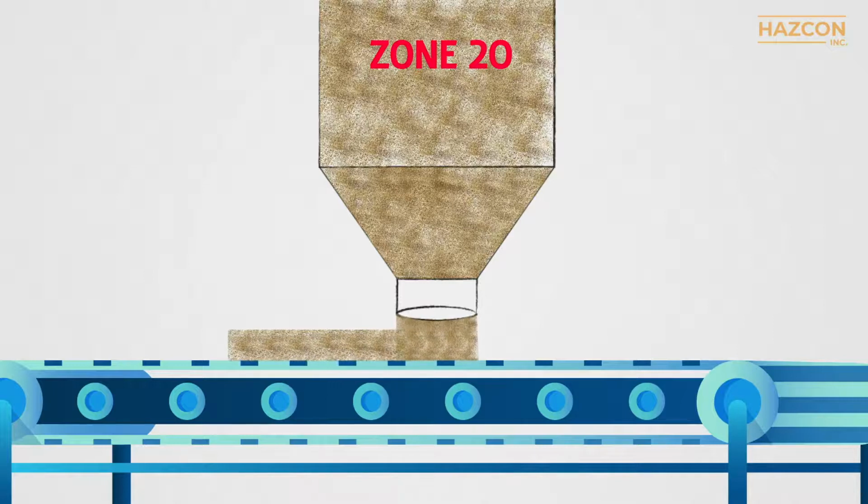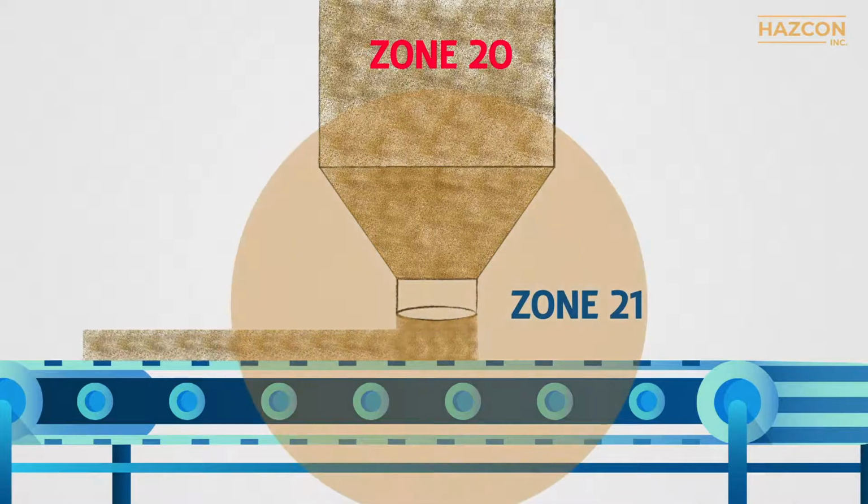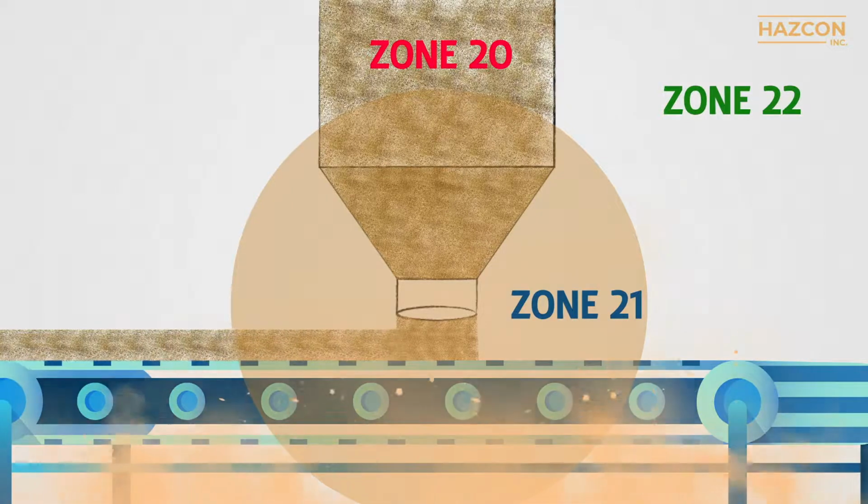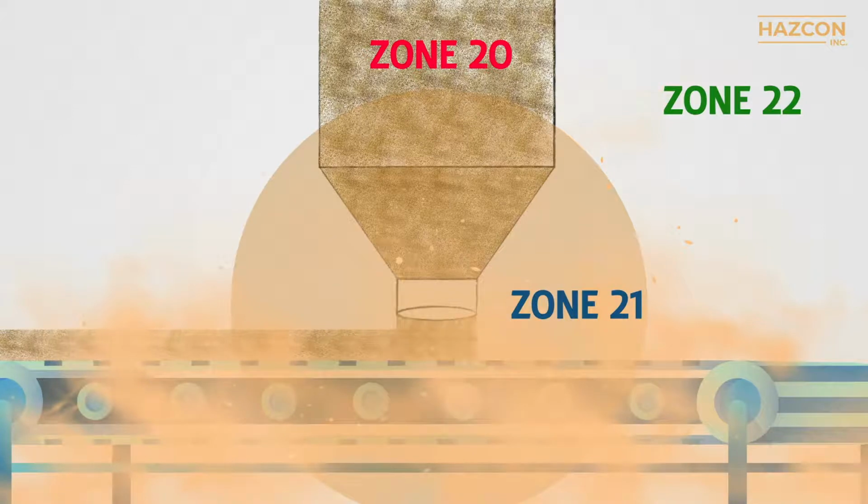The path taken by dust that is allowed to be released from the container when required, called a primary grade of release, creates a Zone 21 environment. Unintended leaks from an incorrectly fitted dust-tight container lid or accidental spillages, called a secondary release, create a Zone 22 environment, as we can see in the graphic. Electrical devices installed in any of these three areas must comply with the requirements for Zones 20, 21 and 22,